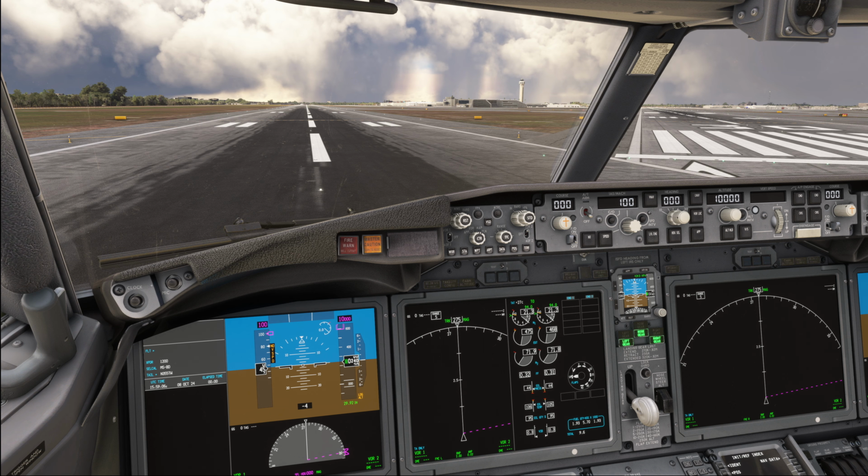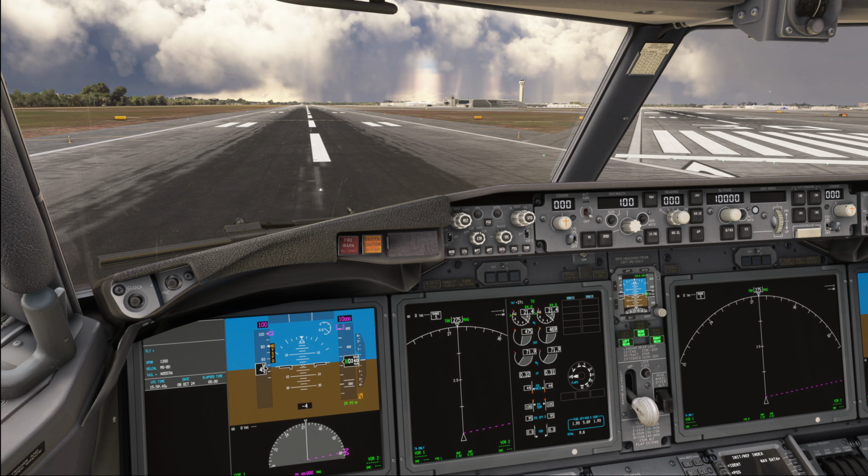Basically, if you are in an autopilot mode that does not offer automatic speed reversion, then you are going to get a disengagement of the autopilot when you are approaching the stick shaker activation, and the flight director will be removed from view until the stick shakers have stopped. Once you're out of the stall condition and the airspeed is above the amber bar, you are going to get your flight directors back, and the pitch mode can transition to a different mode than what was originally selected. The roll mode will, however, remain unchanged.